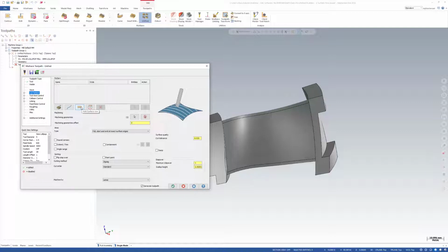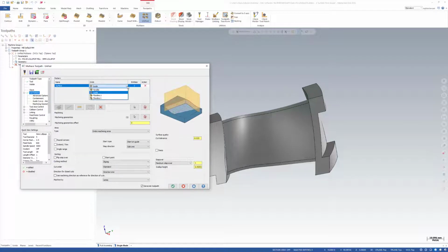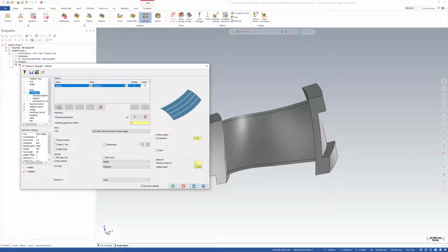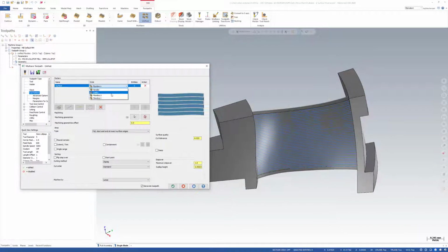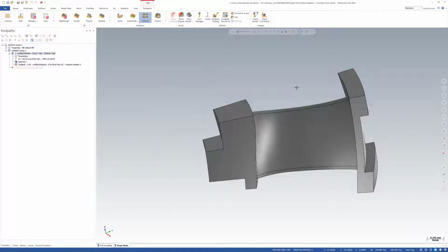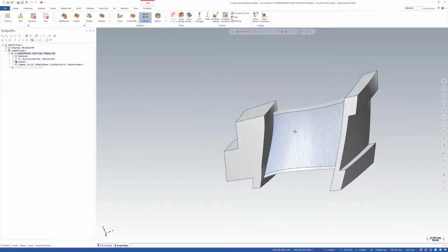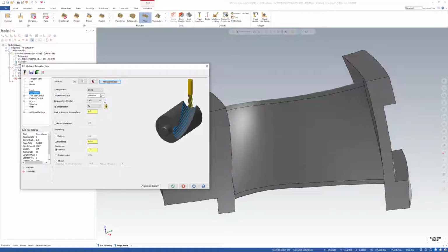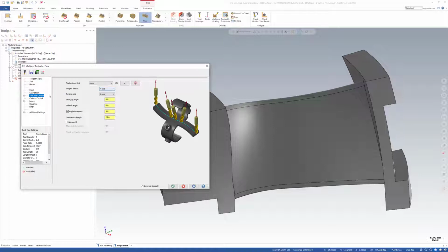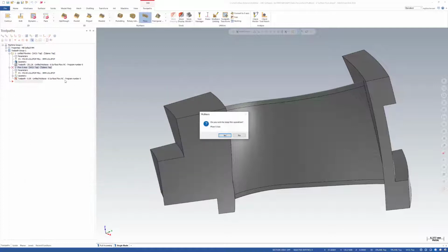Now, in here, you'll see flowline. So let's do a flowline U and preview. Let's see if U, so there's our perpendicular to the flowline motion, or flowline V, and let's generate this toolpath now. So with this generated, this is something that you could do before using multi-axis flow. However, multi-axis flow is getting a little bit old, right? It's not really a whole lot of new development in here. This is one of the original multi-axis toolpaths in Mastercam.